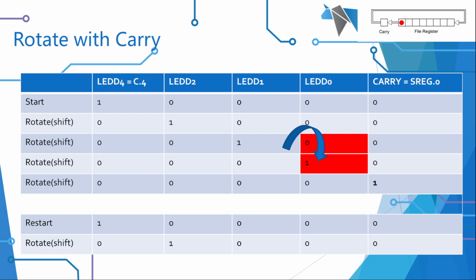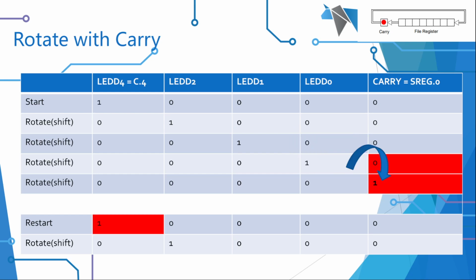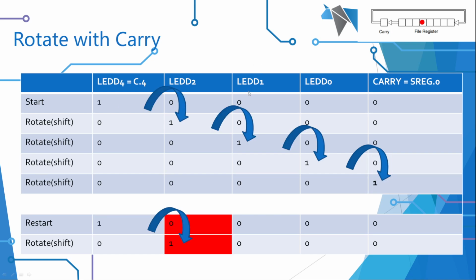And what happens next is, when it goes the next rotation, it puts it in a particular register to say that it happened. And we can test for that. And because we can test for it, and it's called the carry bit, we can restart the process and go back and do it all again. So we can test a thing that's called carry.